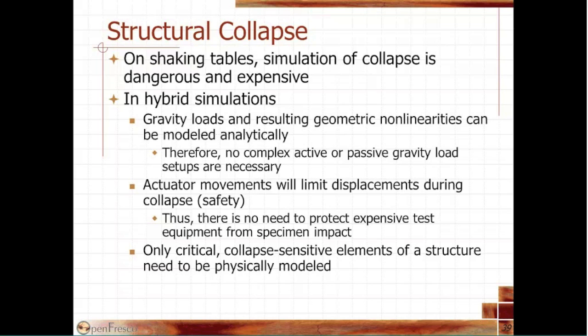However, if we do it in hybrid simulation, it becomes fairly easy. We can apply gravity loads and also the resulting geometric nonlinearities all analytically in the model. So instead of doing it in the experiment, we will put it in the analytical portion of the model. And because we do that, we don't need any complex active or passive gravity load setups.